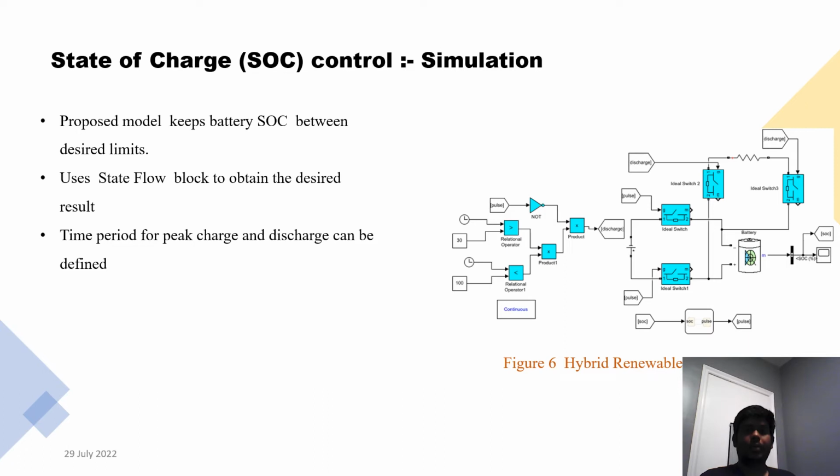One of the very common methods to control thermal runaway and improve the lifespan of batteries would be to control the state of charge, or SOC, of the battery. The state of charge of the battery can be simulated in MATLAB software. We can see in Figure 6 that the proposed model keeps the battery SOC between the desired limits that we choose.